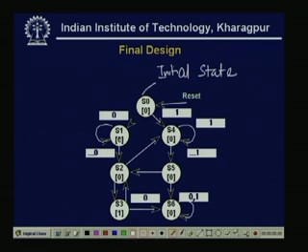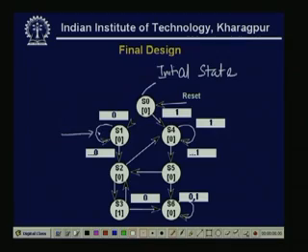After reaching S1, the output will be 0, and for every 0 in the string it stays in the same state S1 and the output is 0. So S1 recognizes all-0 strings.